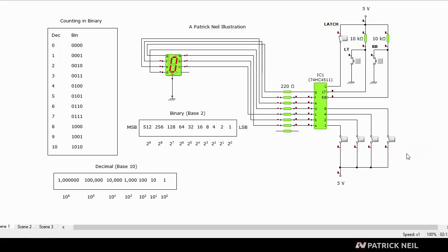In order to understand counters, you must learn about digital electronics and the binary number system. There are two discrete voltage levels used in digital electronics. One is called high and the other is called low. Voltage levels of 2.0 and above are considered high, and voltage levels of 0.8 and lower are considered low. 5 volts has become the standard for high in TTL circuits, so we will use that to represent high. We will use ground for low since it's normally 0 or close to 0.